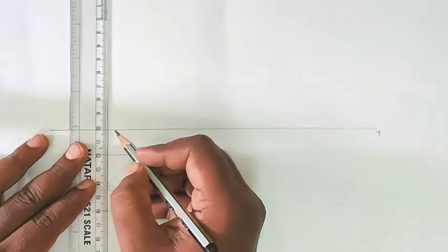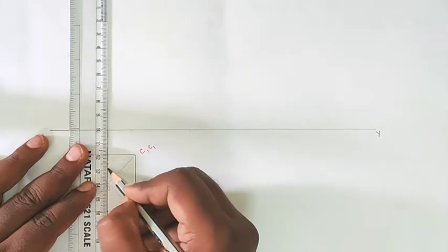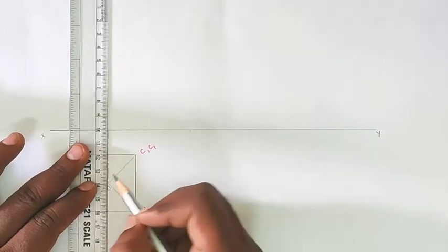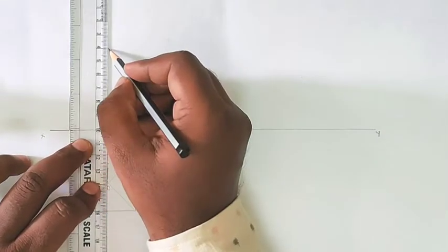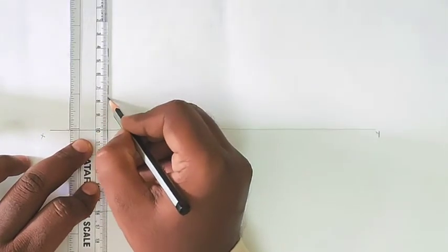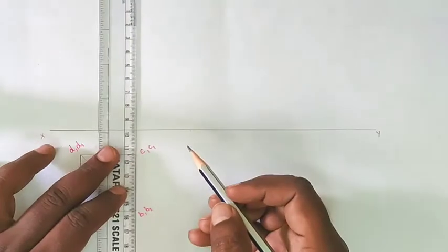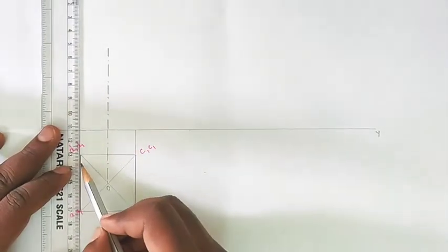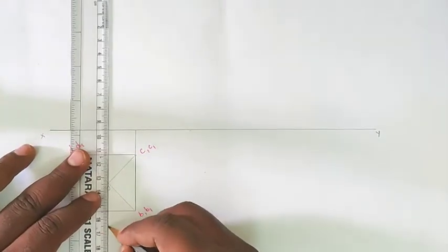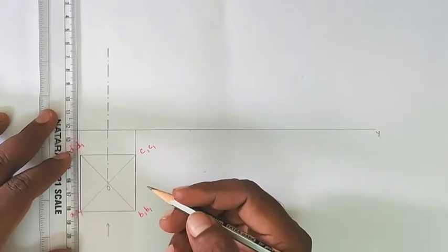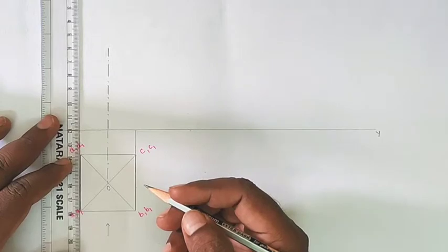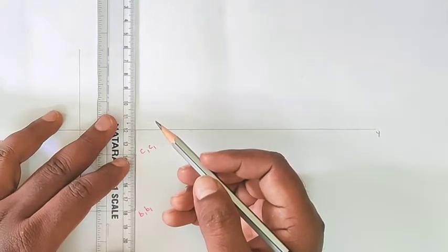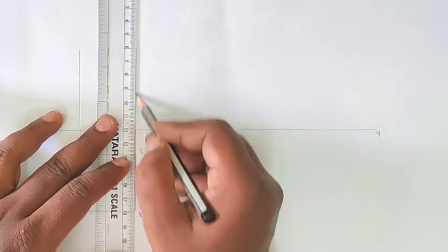After locating the center, the axis is given as 60 mm, so from the reference line, through the center of the top view, take 60 mm and draw the axis line first, then draw the front view of our diagram. Because it is a prism, viewing from the top gives the base, and the front view is obtained as a rectangular face. In the case of a pyramid, we get the front view as an isosceles triangle.